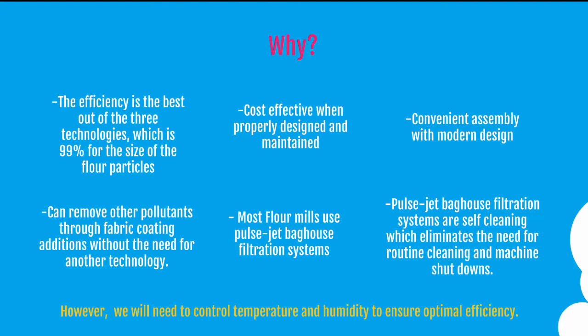Other flour mills wishing to control flour pollution use the pulse jet baghouse filtration system, which shows that the system works well for flour removal. Pulse jet baghouse filtration systems are also self-cleaning, which eliminates the need for routine cleaning and machine shutdowns.